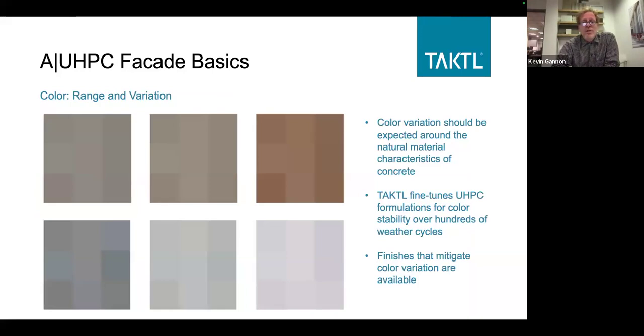So we are a concrete material. It's mineral based. There's a whole range of raw materials that are all mixed together. And not only is the strength and mechanical properties of the material dependent on a curing process, the color is as well. So there will be color variation, just as there can be minor variations in every single ingredient that we're mixing. We do, I believe, a really great job of QC monitoring of everything, but variation should be expected.